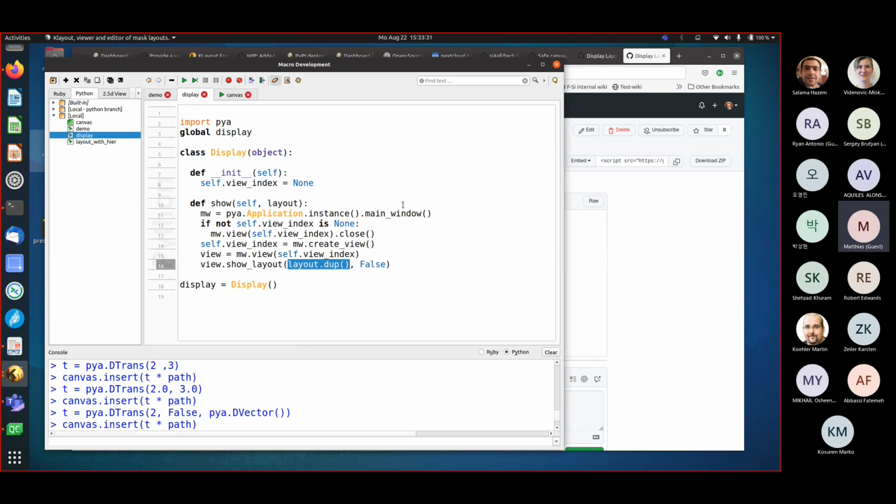If you generate a layout by scripting, it's okay to generate a layout, save it to a file, maybe even show it. But if you expect interaction between both, it's very easy to crash the application if you don't look carefully. So don't be disappointed when you do some experiments yourself, copy-paste code from here, and find the application crashing.